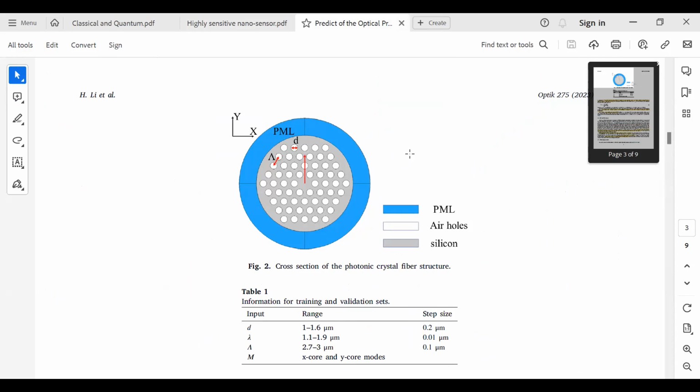And with the data we need to optimize the waveguide itself. So there are a lot of parameters. If we get a more complicated photonic device, we have more parameters, of course. So we need to optimize all of these parameters to obtain the most optimized output for our design. For example, here, as I said before, we need to optimize the chromatic dispersion, the loss, and the effective refractive index. So we need to optimize all of this in this design at different structures.